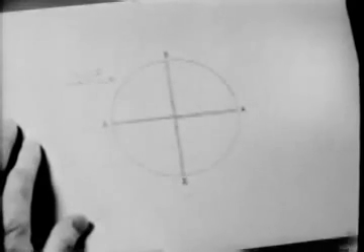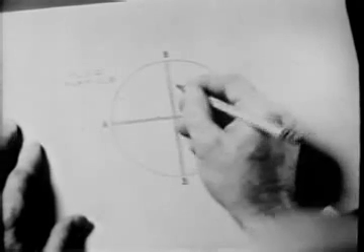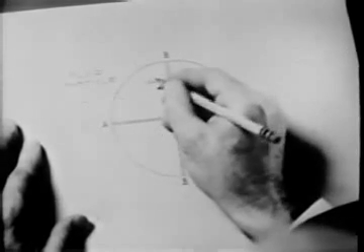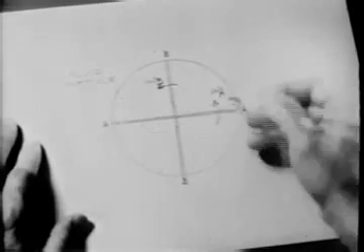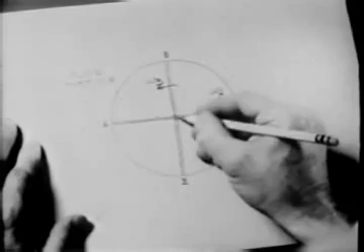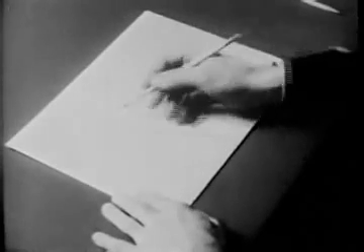In 2 dimensions, the vorticity is the sum of the angular velocities omega A and omega B of any pair of mutually perpendicular fluid lines, AA and BB, passing through the point in question. In a rigid body, every line has exactly the same angular velocity, so the vorticity of a rigid body is the same at every point.